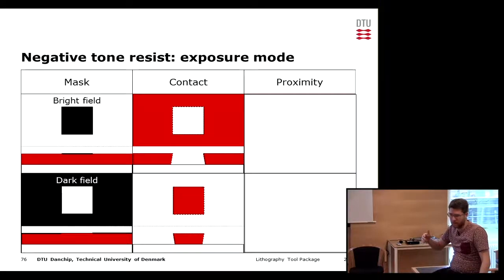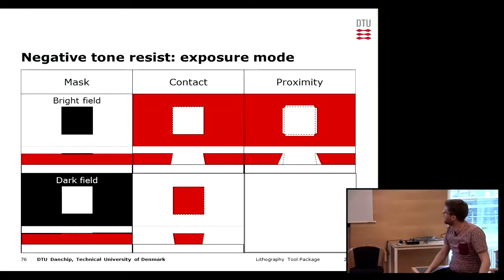Should we have a look? Oh, so the hole is bigger. But that's not what we agreed, right? That's a problem. And we can see that the sidewalls seem like they become more angled, right? So it's more negative. But what is making the hole bigger now? Because the light diffracts, so we get more light below the chrome. Why is the hole then bigger?